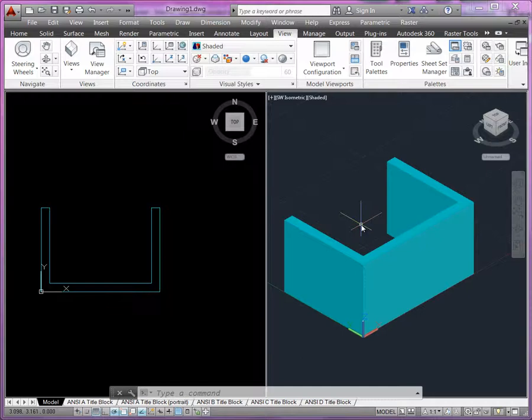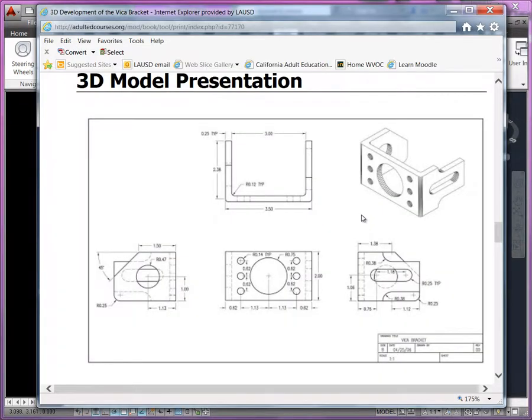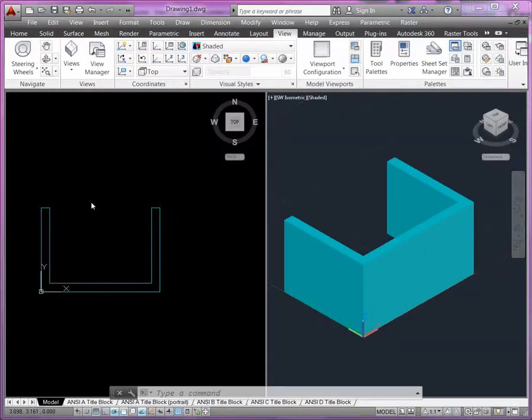So let's try this a different way, because you'll notice that in our model here, we've got filleted corners. We've got a radius of 0.12 on the inside of the front face and on the outside as well, right? Why not combine that with our 2D profile? So let's step back again so I can show you this. I'm just going to undo.